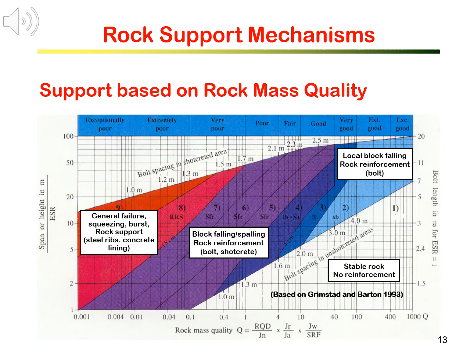Design of rock support for underground excavation is commonly based on rock mass classifications. Again, we use this Q rock support design chart as an example. The design chart gives different design requirements according to the rock mass quality and the excavation dimensions, in terms of spot bolting, systematic bolting with shotcreting, steel ribs, and concrete lining.